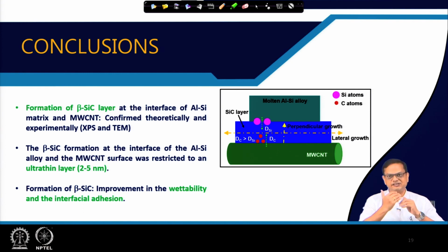The load transfer takes place through the interface. If you talk about delamination, that also happens through the interface. So, we need to understand interface in different kinds of composite materials in different systems. It could be MMC, it could be CMC, and how the interface plays a role in ultimately improving certain properties, that we need to understand. Okay.